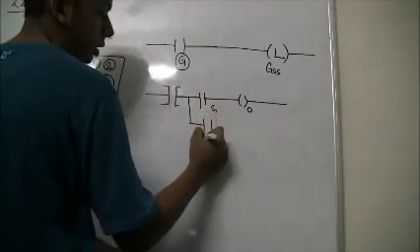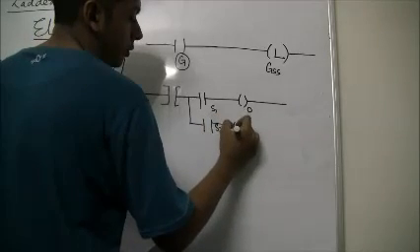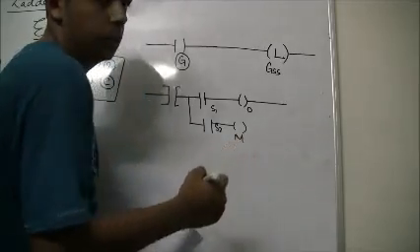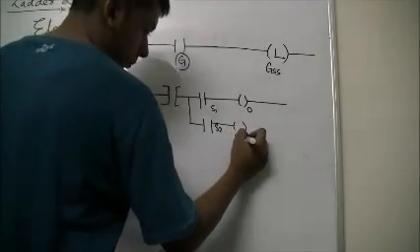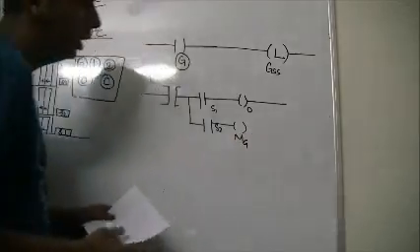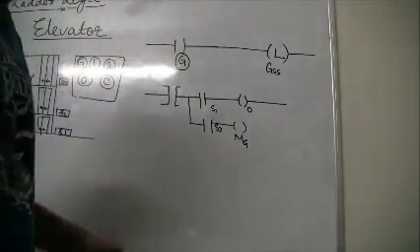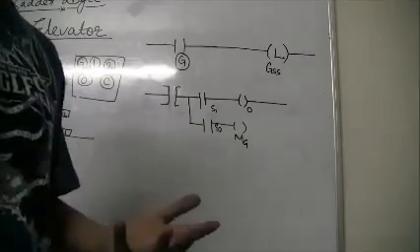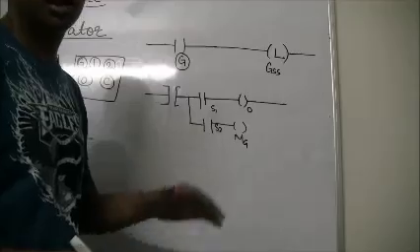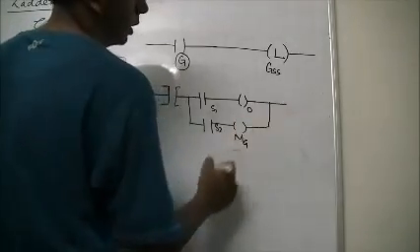If it's S2, then it would first give instruction to MG, right? MG's function is to bring the lift to the ground floor. Now depending on the settings of MG, if the motor is programmed to automatically open the door, then this would suffice and you would close the rung like this.